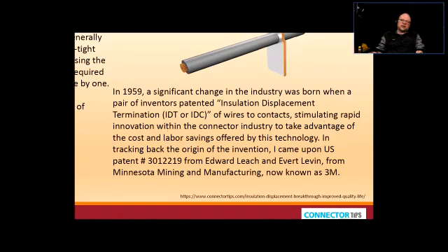Well, actually you have done pretty much all of it right now, because we have done the punch down IDC. You have done it on the individual connectors already, so all of us have done it already. But the next lab, or this current lab that we're still doing, is the 25 pair cable termination. Can you imagine how much longer it would take to terminate all that 25 pair connector onto the 25 pair